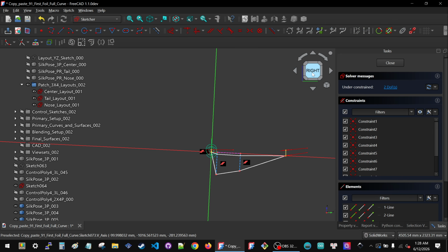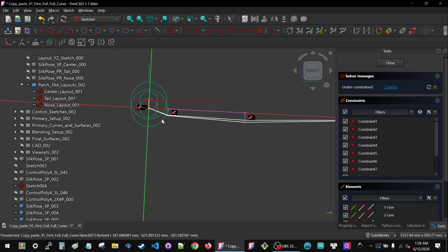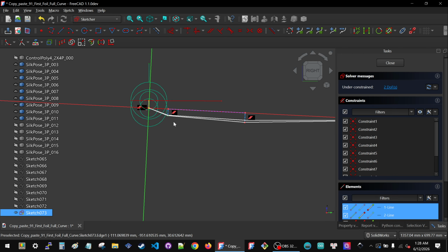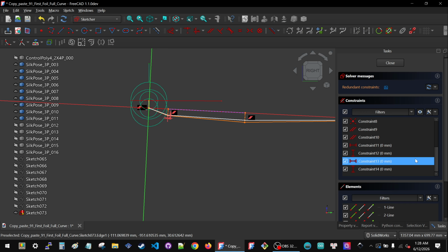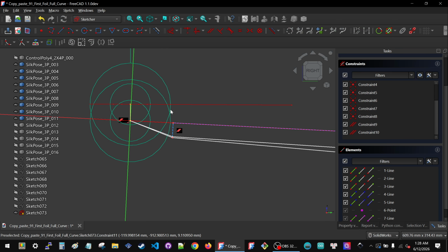Okay. So when I'm looking at this in the right view, I want this sketch to be more or less like this other one. I have my reference at the origin, so I can just, still tricky to pick this point, but I can KL, delete the redundant constraints. Oop, it did a strange thing.